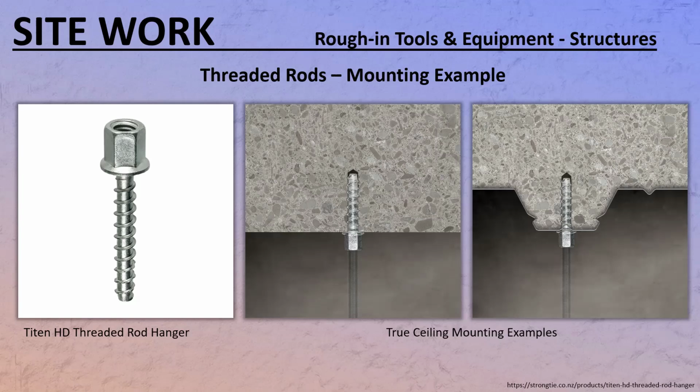And if it is, then you need to take some extra precautions. If you want to drill a hole in a ceiling sprayed with that MMMF, you're going to have to clear that little bit, which means you're going to disturb it, and it's going to get airborne. So you're going to need proper PPE, almost like dealing with asbestos, and then you drill the hole. Take what I just said seriously, because it can harm your health. And one of those things is that it doesn't harm your health right away. It comes out years later.